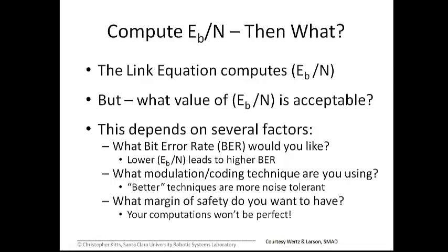And this is certainly something we will review during the in-class session. But to give you an idea, it depends upon how many bit flips you're willing to take. The worse the quality, the more bit flips you're going to have, the more noise will corrupt the digital information. And remember, we talked about how we went digital, we went discrete, to be immune to noise. But if you have a high enough level of noise, it will even corrupt digital data. And the more noise, the more that corruption. So part of that is how many bits per thousand you are willing to suffer bit flips.